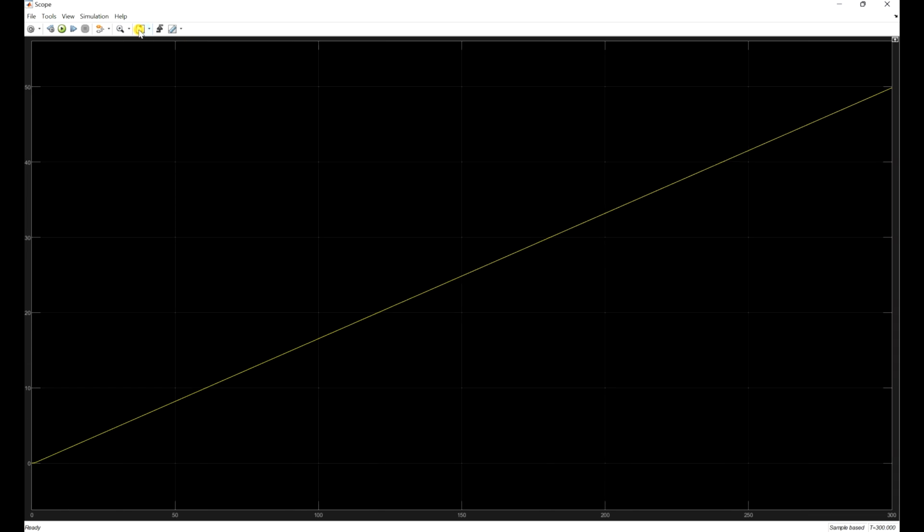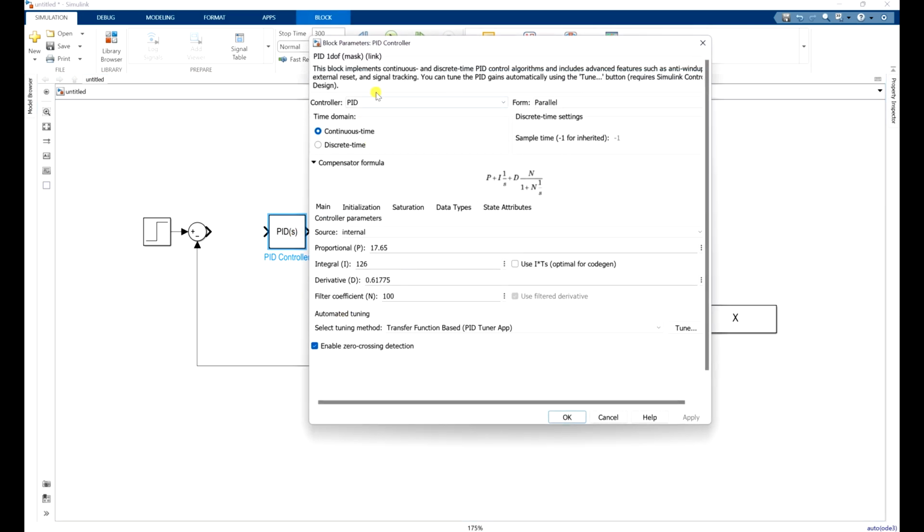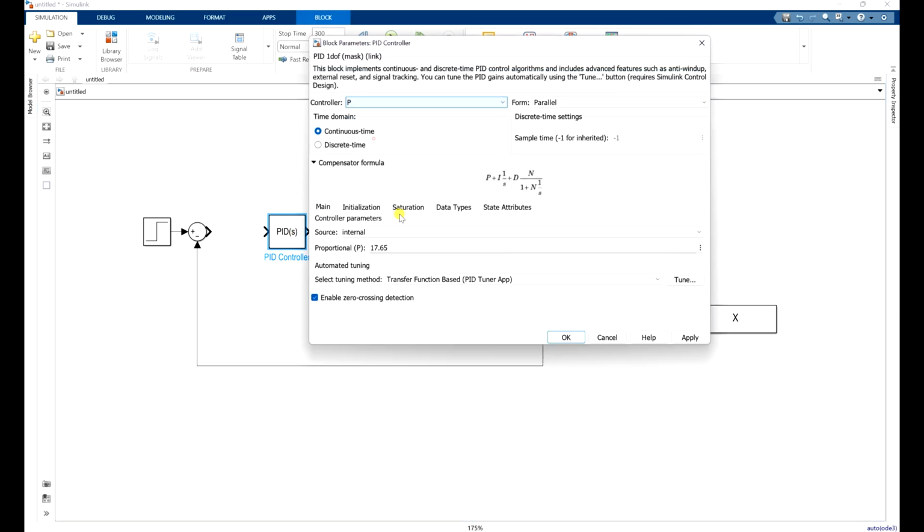So you can see that the system is still going up. So we don't have the S shape. It doesn't even reach a steady state response. So what I'm going to do now is use the second method, which is a closed loop method. So I have normally a closed loop as I want, like this.